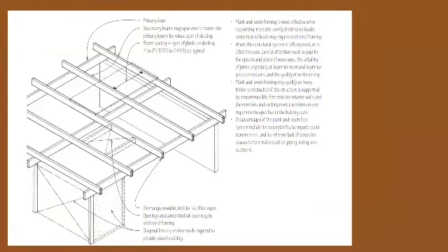Plank and beam framing may qualify as heavy timber construction if the structure is supported by non-combustible, fire-resistive exterior walls, and the members and decking meet the minimum size requirements specified in the building code. The disadvantages of the plank and beam floor system include its susceptibility to impact sound transmission and its inherent lack of concealed spaces for thermal insulation, piping, wiring, and ductwork.